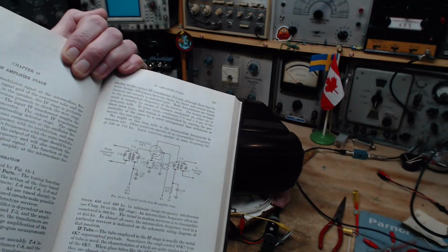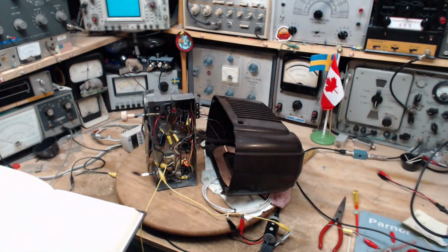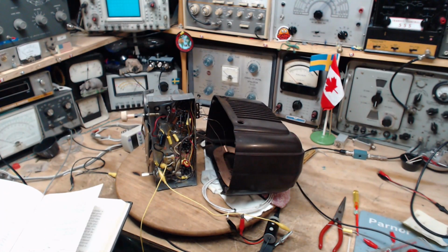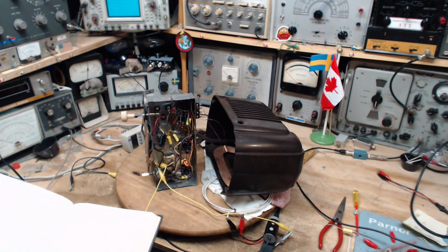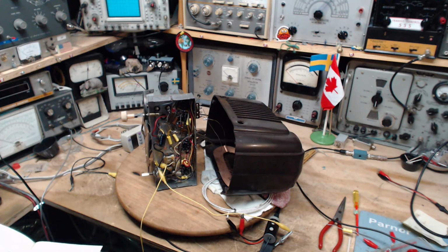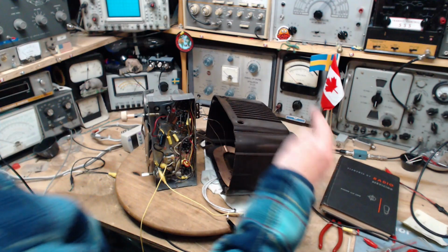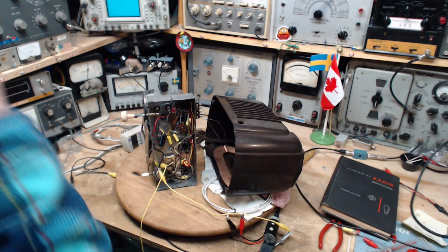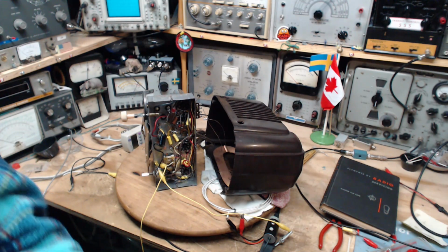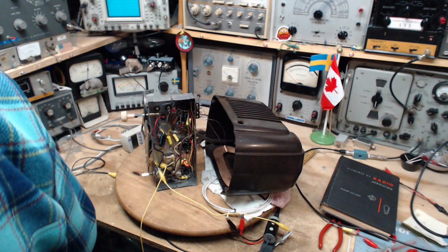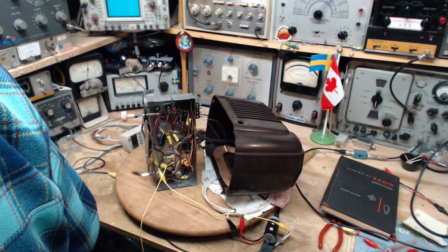Well, they've just gone and hooked the wire up to the B plus and forsaken the capacitor, which I think is a big problem. How do you handle this situation here? The only thing that comes to mind is detuning the IF, trying to reduce the Q on the IF and maybe broaden it a bit, in order to make the radio less likely to oscillate. I don't know. That's interesting. Coffee time.